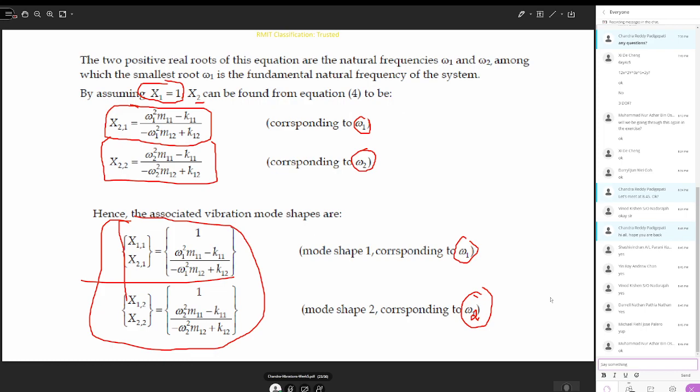All right, so the derivation of these expressions is not important, you can always use the expressions to calculate the amount of displacement. So for two frequencies, you have two displacements. Okay, the mode shape refers to how the displacement x2 varies with respect to x1. So the variation of displacement is referred to as the mode shape or the modal shape.